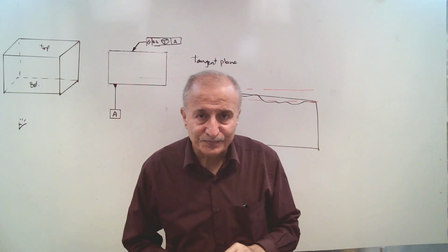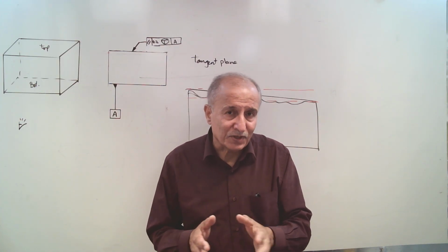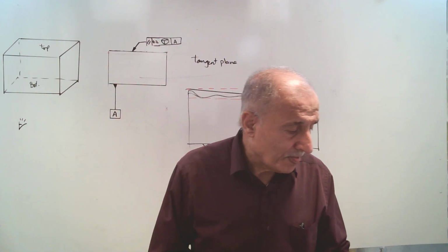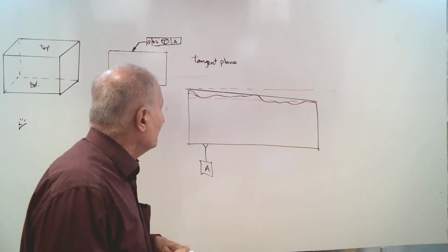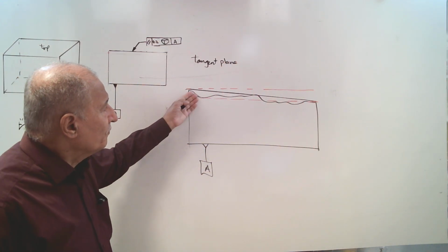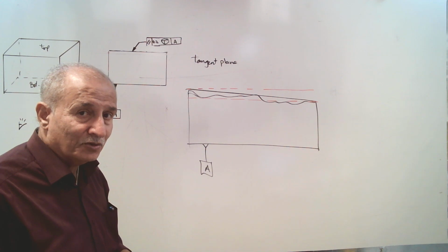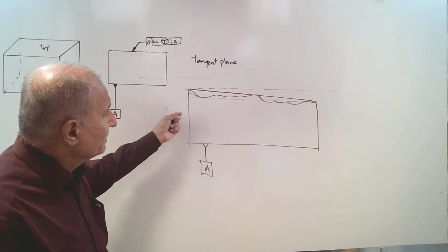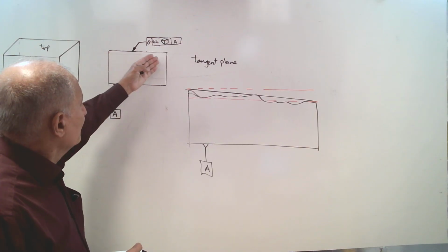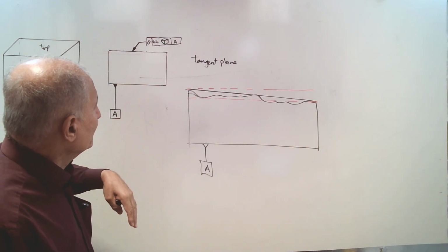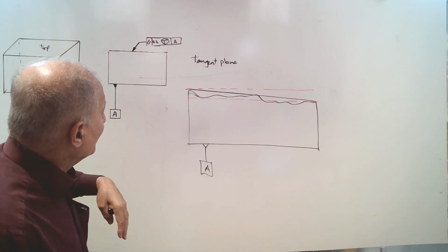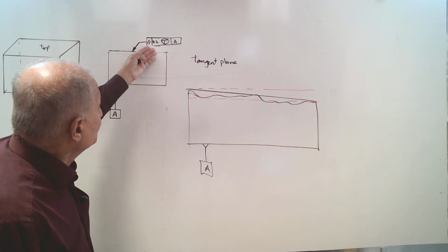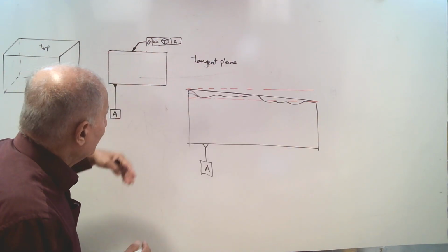That's everything that we can say about the tolerance, but it depends. Sometimes how flatness can be controlled here is the question. You must look at whether this surface has the only geometric term that applies to it, parallelism.